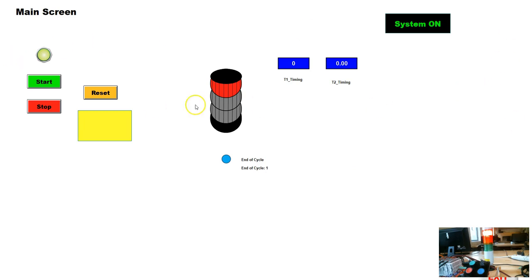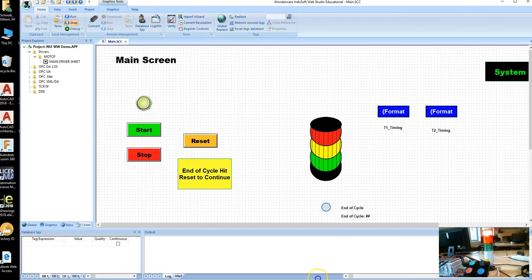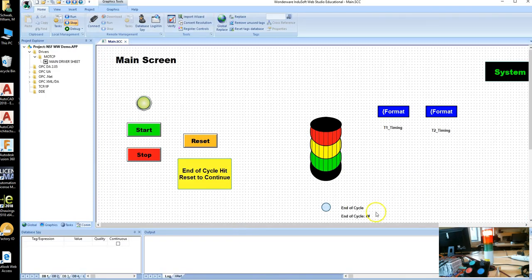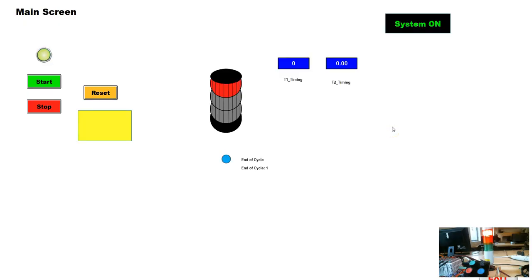It's especially helpful because right now the Wonderware kind of occupies the whole screen, and if we want to find out what's going on in our PLC, we have to exit out of here and go into our PLC, and again, you can't see it real time. But if you put that in there, except for the little lag in the software delay, that shows you exactly what that signal is doing. It's really handy. I use it on all the programs, and so that's putting a little more visualization in here.